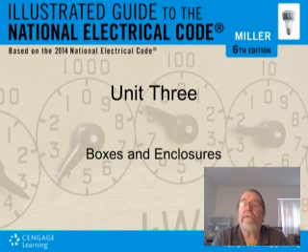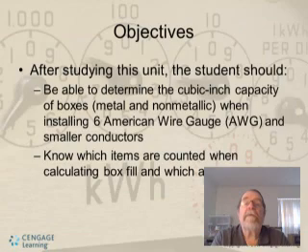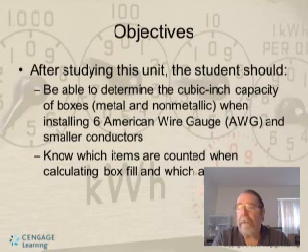Today we're going to discuss Unit 3, which is boxes and closures. The objectives of this unit are basically, after you study this unit, you should be able to determine the cubic inch capacity of the boxes, both metal and non-metallic, which are the plastic boxes for outlets and for switches, and